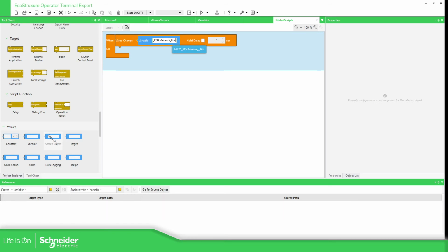Dot bit dot aux motor dot. Here we have more information: initial value, max value, value, and quality. So when the quality is different, okay, when the value, if I know wrong, the quality is 1, it means that we don't have communication, okay. It means that the PLC, we don't have connection to the PLC.